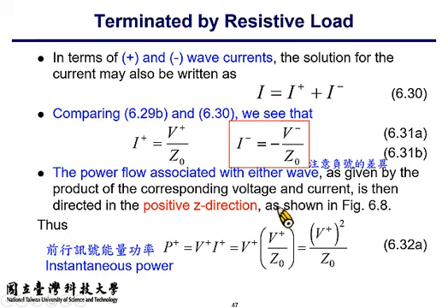So remark that the voltage over current ratio shall equal the magnitude of the characteristic impedance for both the forward-going part and the backward-going part. For signals going in the transmission line, the voltage over current ratio is a constant based on the transmission line geometry, based on the configuration of the transmission line.